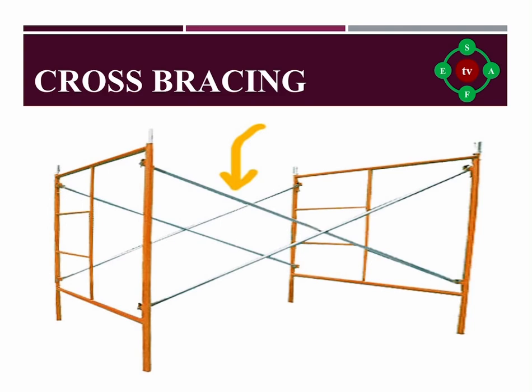Cross bracing. Cross bracing is a technique in the construction industry whereas braces are crossed to support framed structures such as scaffolding. Using this technique makes frames and structures sturdy and able to support and hold heavy loads. As a standard, the cross point of cross bracing used as a top rail should be between 38 to 48 inches above the work platform.